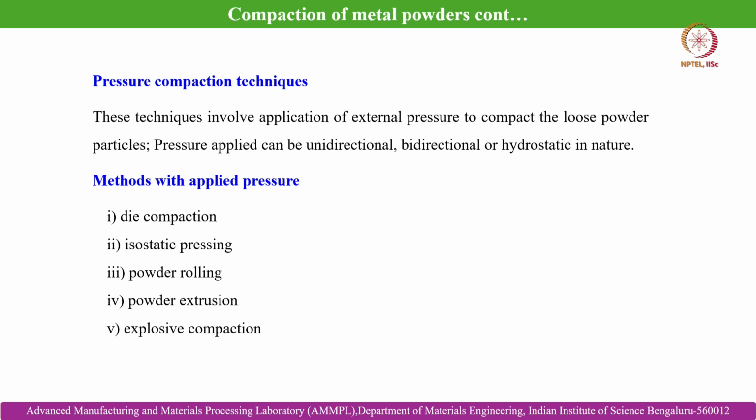So, the pressure compaction techniques. We have discussed vibratory compaction, we have discussed loose powder compaction, where we are not applying any pressure, and now we move on to the pressure compaction techniques. These techniques involve application of external pressure to compact the loose powder particles. The pressure applied can be unidirectional, bidirectional or hydrostatic in nature.